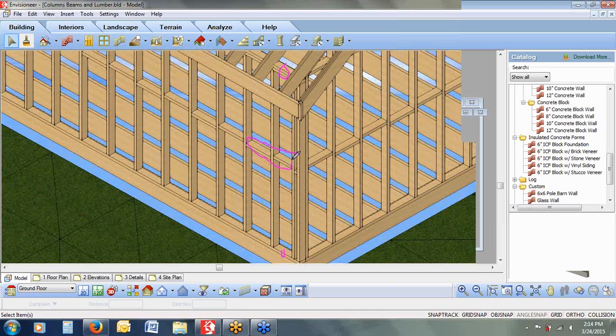And there's our row of blocking halfway through. The others are the floor joists that are underneath it for the floor framing. So it's following those rules that I set up to use that framing. When it comes along to these studs, it looks at the length and the height of the wall, an 8-foot wall, and says, I can use a 92 5/8 pre-cut stud.